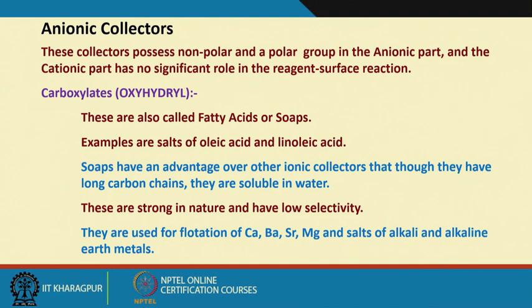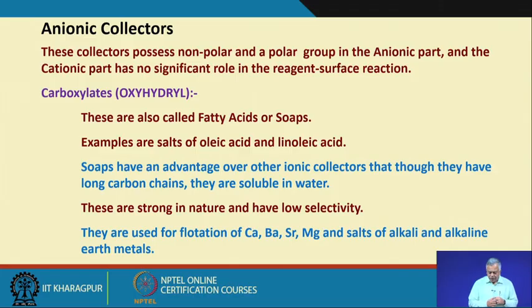That polar and non-polar group will try to make my targeted mineral surface hydrophobic. In that context, soaps have an advantage over other ionic collectors in that although they have long carbon chains, they are soluble in water. Why I mentioned long carbon chains, we will discuss later on.